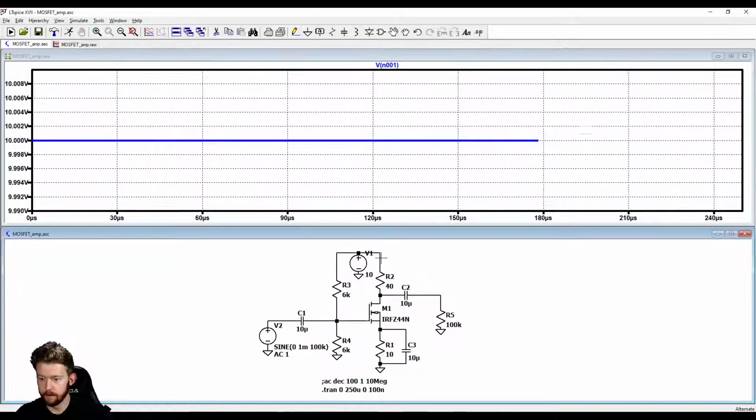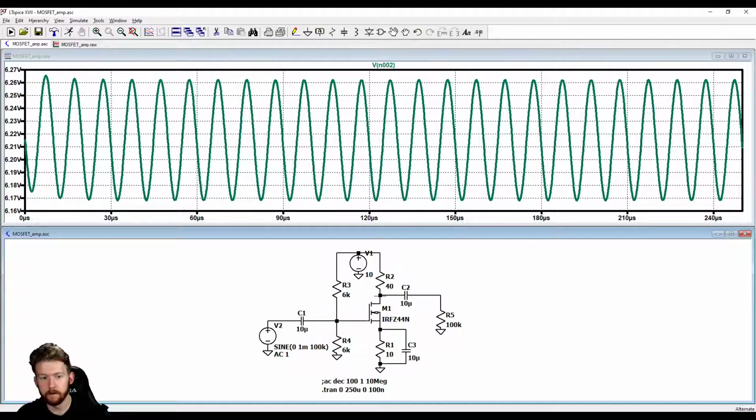So now, again, we have 10 volts as our supply. This is our V out before the capacitor, okay? So we're oscillating at about 6 volts, okay? So we did a pretty good job at a first glance at this. We're at about 6 volts. Maybe if we did a little bit more tuning, we could get it right where we need it to be.